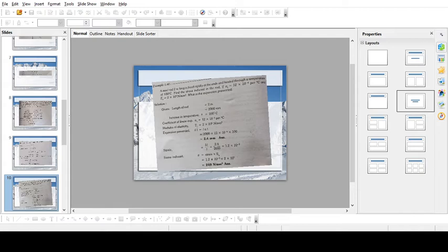So it is sigma 1 by E1 into L plus sigma 2 by E2 into L should be equal to L alpha 2 T minus L alpha 1 T. Now I'm taking L common on both sides, so it will simply get cancelled, and the leftover thing will be sigma 1 by E1 plus sigma 2 by E2 is equal to T into alpha 2 minus alpha 1. So L got cancelled on both sides.